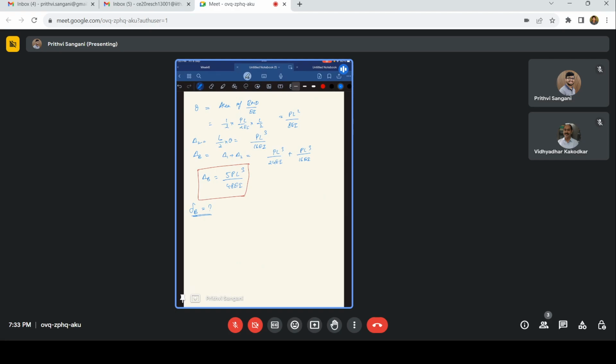Like I said, if you have some inclined force, let us say P, then you will also have a horizontal reaction at A and at B. Right now we are not dealing with such questions, only gravity loads, which are vertical loads. So we have two equilibrium equations and four unknowns. 4 minus 2, the degree of static indeterminacy is 2. So we have two redundant forces.